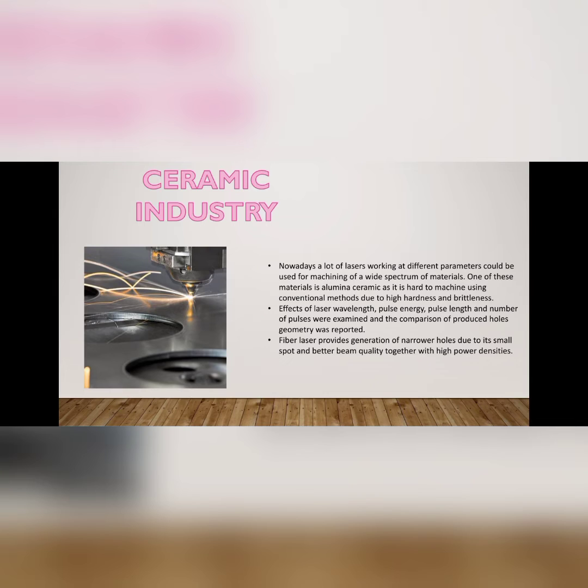Coming to the part of the ceramic industry, in the laser and ceramic industry nowadays, a lot of different parameters would be used in machining a wide spectrum of materials. One of these materials is ceramic, as it is hard to machine using conventional methods due to high hardness and brittleness. Effects of laser wavelength, pulse energy, pulse length, and number of pulses were examined, and comparison of produced hole geometry was reported.